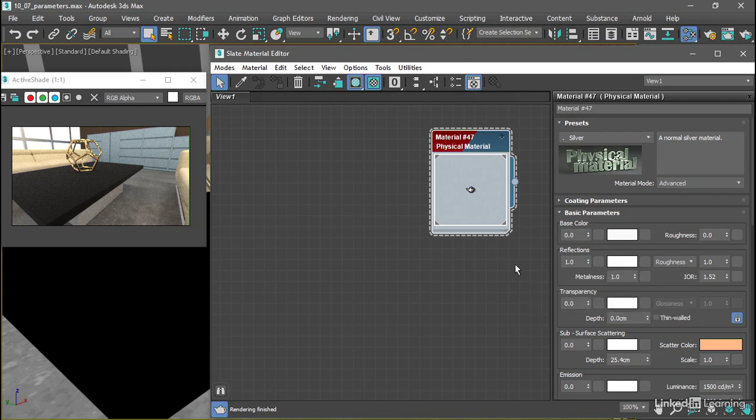Additionally, now if you look closely, you'll see that there are 2 roughnesses. The one that we were adjusting previously was the specular roughness. And that's now moved into the reflection section. So this is the roughness that we're used to. But there's additionally now another roughness in the base color section. That's diffuse roughness, and it's there as an additional parameter for certain types of effects such as unfinished ceramic. That doesn't really apply in this situation.